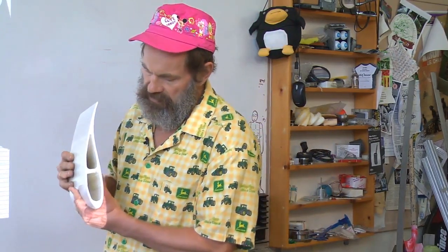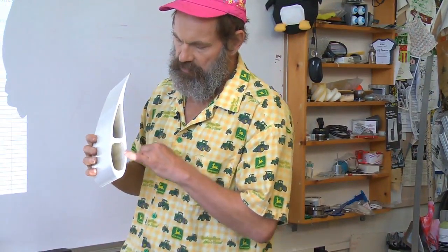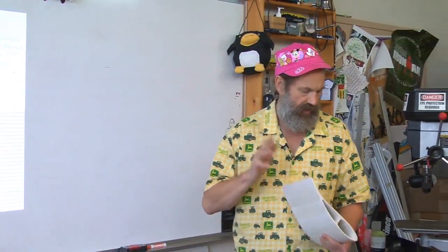This is the section from a Berge wind turbine blade. Notice how, and this is a pultruded fiberglass, this aerodynamic section, this airfoil, was actually pulled out, or pultruded, as one piece, very, very torsionally stiff, bending stiff, but made of simple plate sections. So remember the power of the neutral axis theorem in using extrusions and extrusion type processes to achieve very, very high stiffness and strength from what otherwise may be thought of as soft plates.